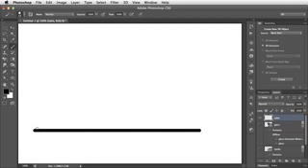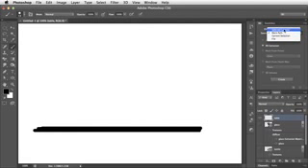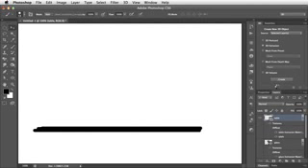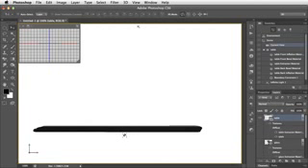Let's add another line on top of this. So dab with the brush, hold the Shift key to draw it across, and maybe an extra small reveal on top. And that will give us a little bit of shape to the edge of our table. This time we're not working from a path, so we can't use work path as our source. We'll change that to the selected layer and hit Create. And there it is.